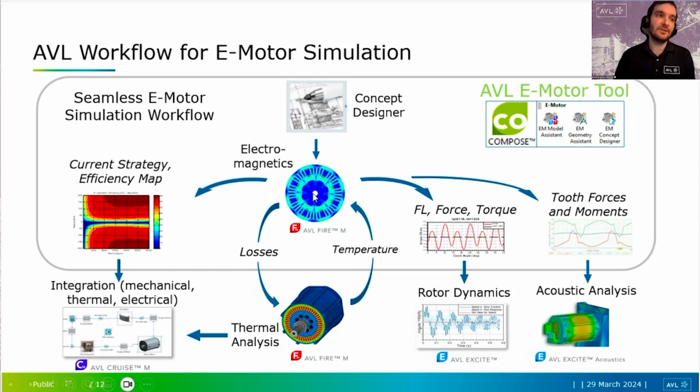So it'll set up the mesh for you, it'll set up the physics boundary conditions, because while you're designing your concept, you're identifying where's the magnet, what are the geometries, and it'll actually create the mesh, the drawing for you and the mesh, and do all of the simulation on the back end for you. So you don't really need to even be a CFD expert in order to set this up.